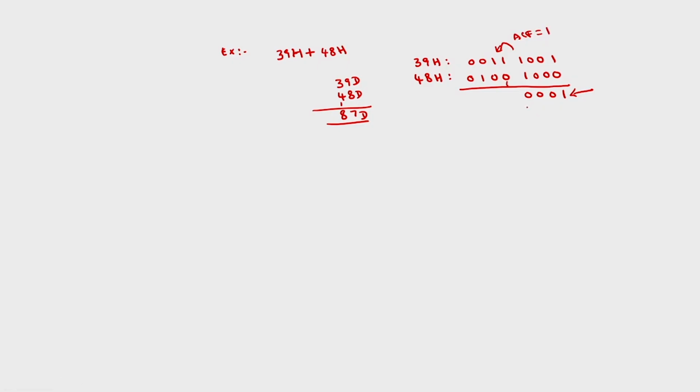So because of this, the instruction adds 6, and here this will be 1 plus 0 plus 1 is 10. Neither of these conditions is satisfied. This magnitude is 8, which is less than 9, and there is no carry flag, the carry flag is reset. So this instruction simply adds 0000.